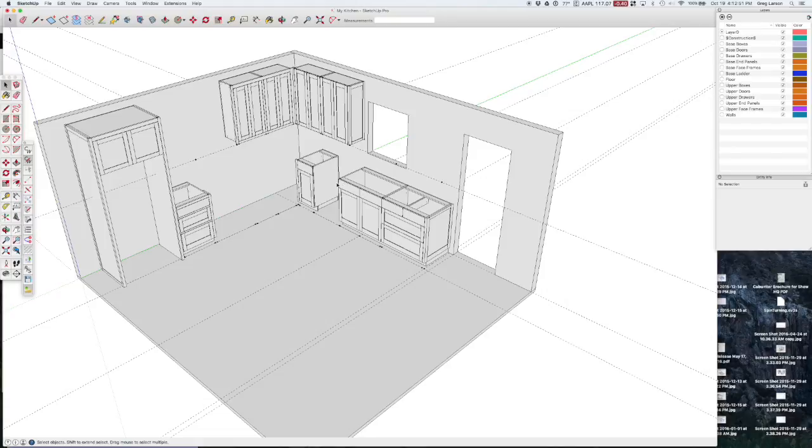Now, every one of these cabinets, every component in every one of these cabinets has the parameters saved with the cabinet and the components of the cabinet that were set when the cabinet was drawn. So in other words, whatever parameters were set at the moment that cabinet was drawn, those will be saved off with the cabinet. So you could have every single cabinet in your kitchen be a different construction style or a different combination of parameters, and those parameters would be saved with the cabinet.